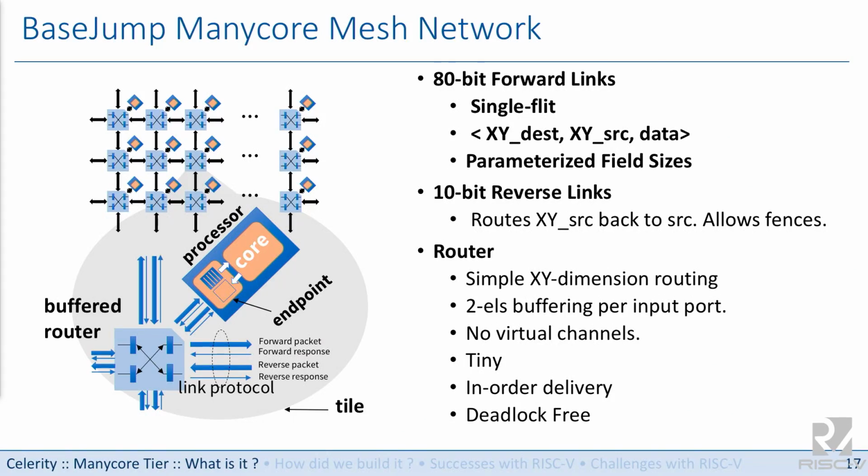Okay? So, and the routers are absolutely tiny. We don't use virtual channels. They provide in-order delivery. They're deadlock-free. And we have the absolute minimum buffering you need in the system to keep the area down.